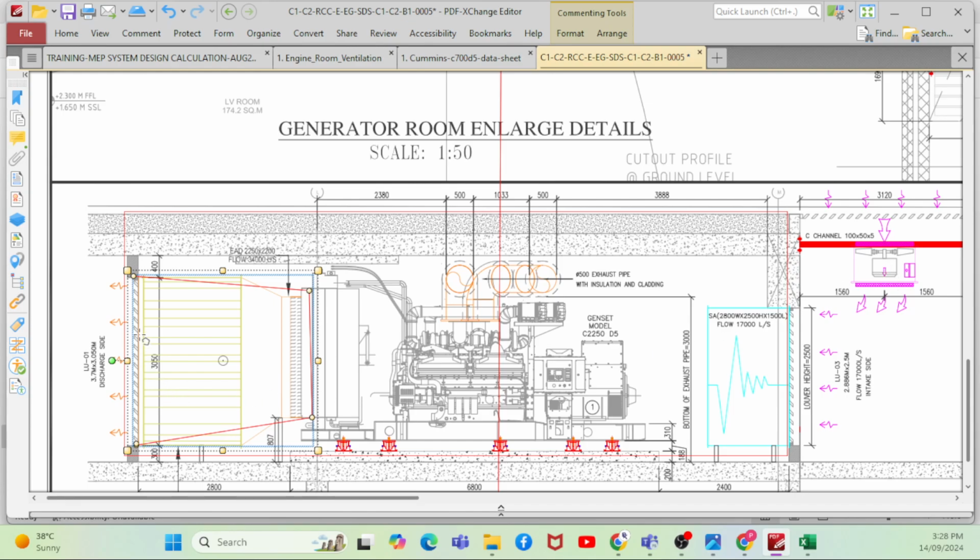Whenever you design the accessories at the very initial time, you design them with a very low pressure drop. But sometimes you will have to communicate this with your manufacturers. You have to give them your radiator fan pascal requirement as well, so that they keep this in mind. Now whatever accessories pressure drop you calculate should be less than 127 pascal.